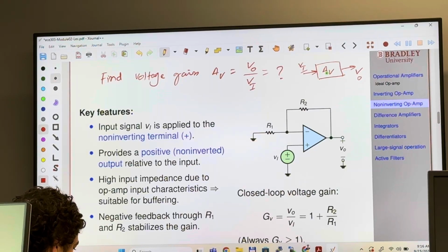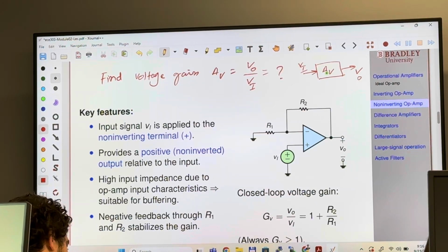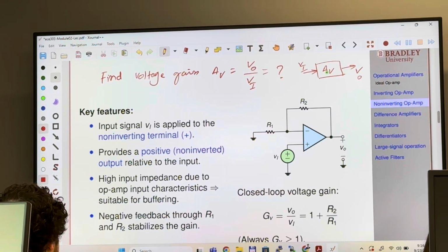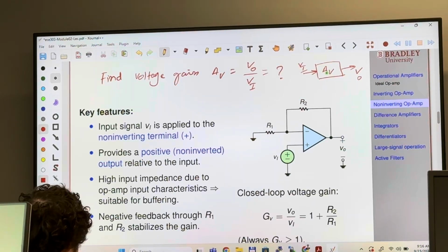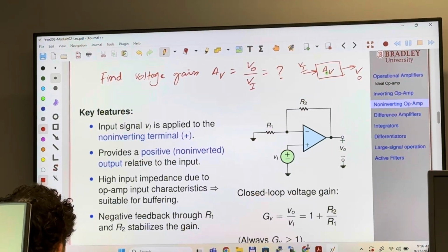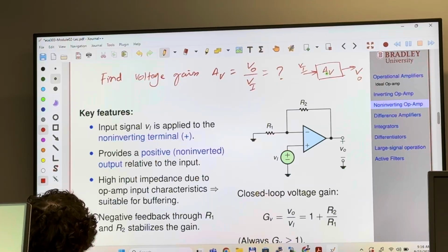Okay. So those who are taking mechatronics, you see the gain that we have in a temperature sensor. The gain is implemented in the temperature sensor. So this temperature sensor, the thermostat, has some gain. In the data sheet, you will see a gain of, let's say, 10 millivolt per degree Celsius. So for each degree Celsius, the voltage generated by this temperature sensor is 10 millivolt.